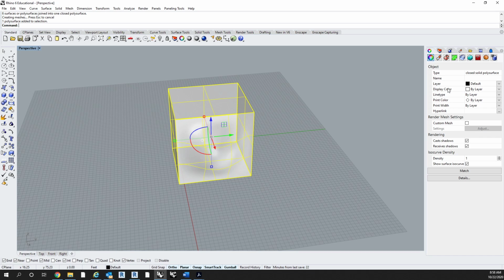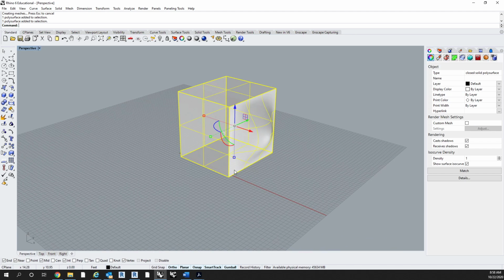One thing to be aware of is solids are much easier to manipulate than singular surfaces. You can definitely bring in singular surfaces into Revit, but in terms of manipulating materiality or actually creating conceptual mass elements from an imported CAD file, solids are typically the best. For some reason, Revit can just read that best, because really in Revit, there doesn't exist singular surfaces. Of course, there are singular faces of objects, but just like in real life, everything has a thickness. And so singular planes, singular surfaces don't really compute well within Revit.